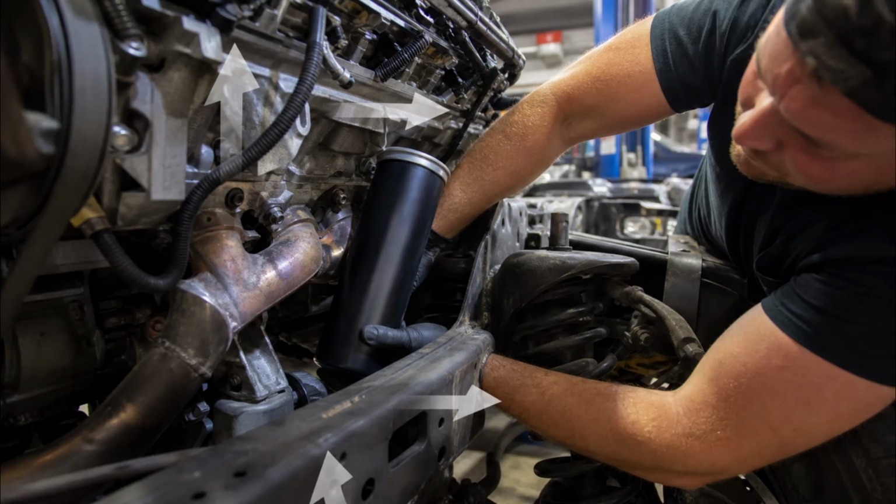The fifth difference is physical size. A taller or wider filter may hold more oil and have more filter media, but that does not mean it belongs on your engine. The filter still has to clear the engine bay, exhaust components, frame, suspension, under tray, and sometimes the radiator fan or steering parts. If a filter is too long, it may hit something during installation. Worse, it may fit while the car is parked, but contact another part when the engine moves on its mounts. Engines are not perfectly still. They twist slightly under acceleration and load.